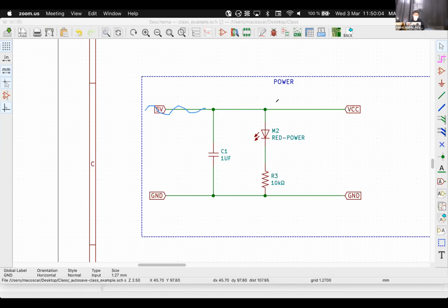And that depends on your power supply. Imagine that you have connected a motor there. A motor, like an electric motor, has a lot of inductance, and that generates a lot of noise. Also because you're actuating a motor, and that varies the load, and connecting one part with a motor with another part that has a microcontroller is not nice. So maybe you end up with something like this. Or imagine that on this side, you have a very sensitive sensor or a noise circuit that if you put a static noise in it, then it sounds bad.